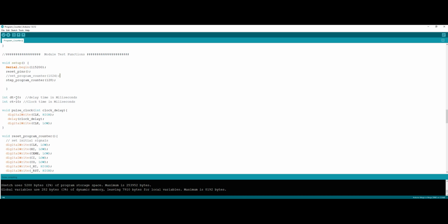When we run those control signals and bring them high or low, it happens really fast, and we would not see anything on the LEDs. That's why we could increase that number to, let's say, a second or so, and this way we'll be able to actually see the LEDs blinking on our LED board. So I'm going to set that now to 1000 milliseconds, which is equal to 1 second.